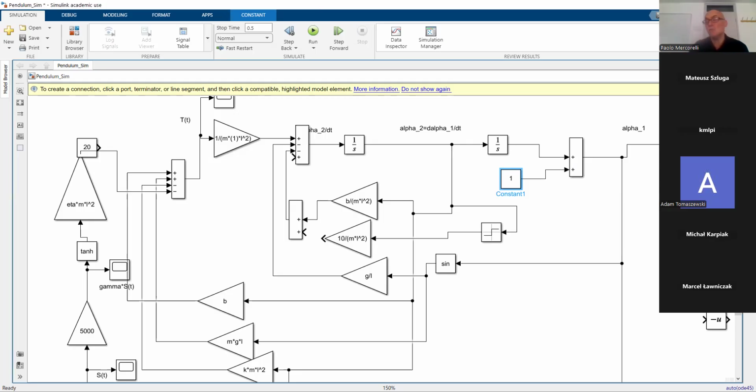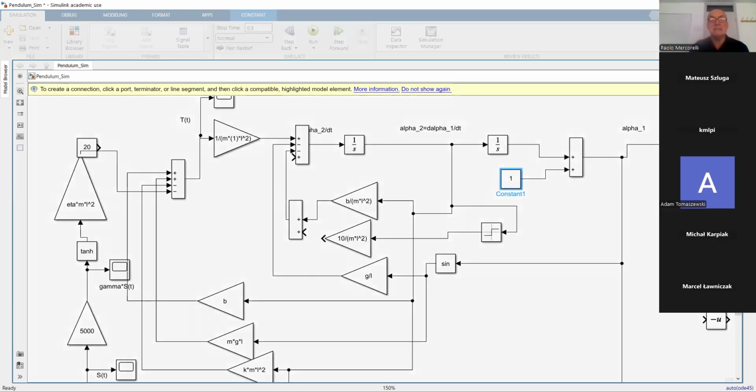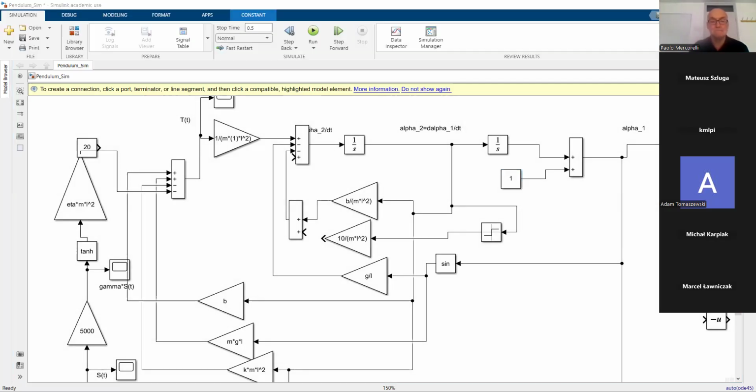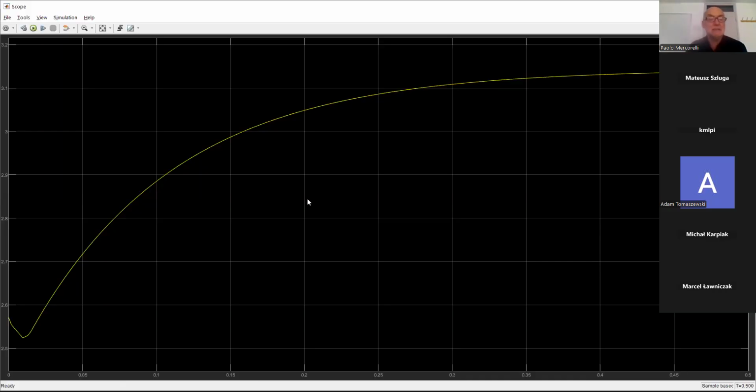Otherwise, I have to increase eta, and therefore the I value at the beginning. You can see that independently of the disturbance directly in output, at the beginning the control law has some difficulties. Why is that? Because there is also a delay in order to achieve s equals 0. When we are at s equals 0, theoretically, we are insensible.